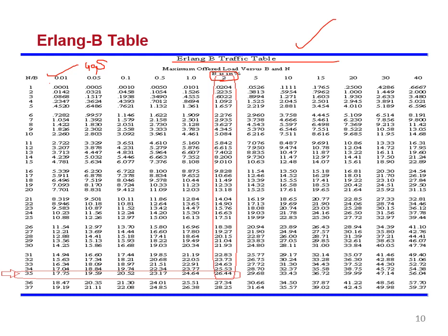For grade of service 2%, how many Erlangs of traffic you have to cater to for the number of channels? If 1 channel is there, it can cater up to 0.02 Erlangs. 8 channels are there, because one TRX can support 8 channels. One transceiver hardware in the BTS can support 8 channels. 8 channels means 3.6 Erlangs. So one TRX can support 3.627 Erlangs.